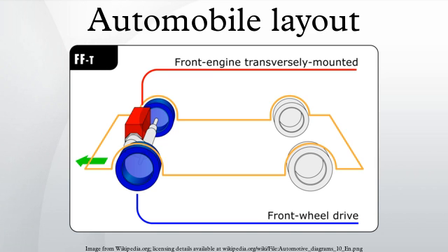Transverse and longitudinal engine 4WD systems derived almost exclusively from front-engine, front-drive layouts, fitted to luxury, sporting and heavy-duty segments, for example the transverse engine Mitsubishi 3000 GT VR4 and Toyota RAV4, and the longitudinal engine Audi Quattro and most of the Subaru line. For a full explanation of 4WD engineering considerations, see the main article on four-wheel drive.